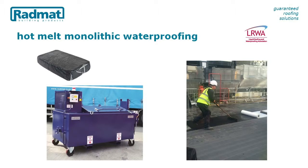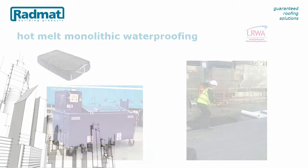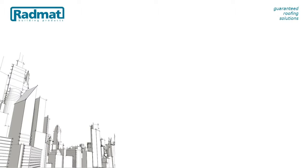Radmat have recently developed an electrically heated melter which covers these considerations, but this creates other method statement requirements related to the power levels required. The final health and safety consideration is the application of the molten hot melt, which is applied at between 180 and 210 degrees C. Again, a comprehensive method statement and suitable PPE are required. Later, we'll look at detailing and standards.